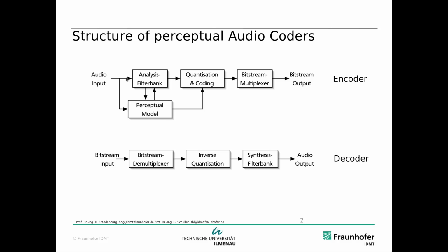So the analysis filter bank decomposes our audio input into subbands of different center frequencies, which are covering the entire spectrum of our audio signal, followed by downsampling such that we don't increase the total data rate. Here the synthesis is doing the inverse. Here we would upsample and then filter and add all those frequency components up such that we get a full spectrum audio output.